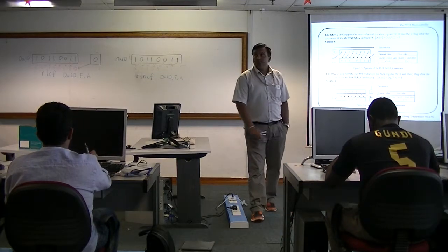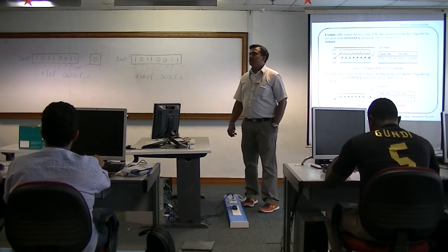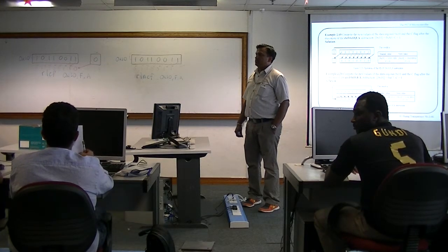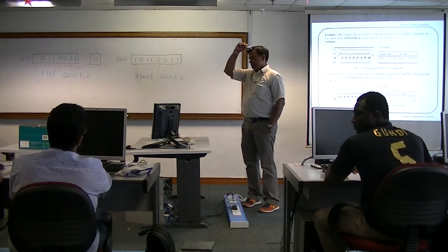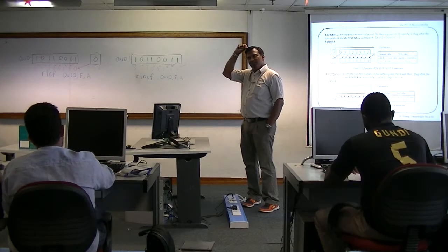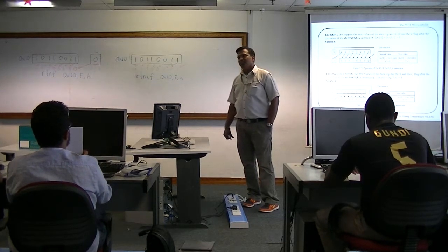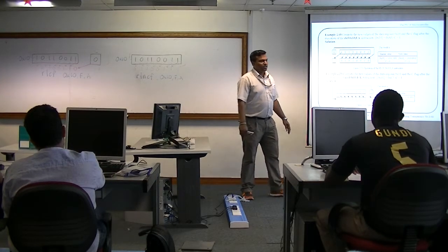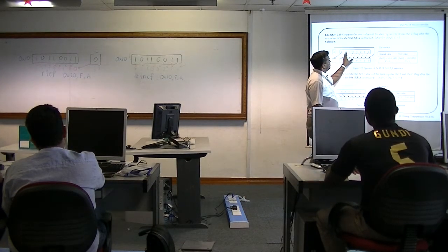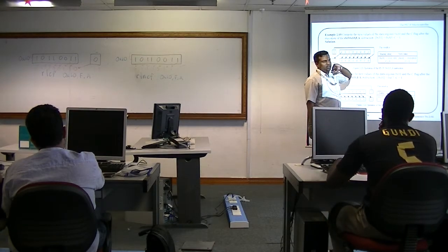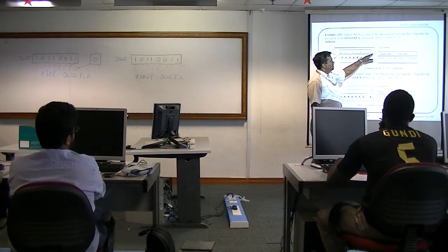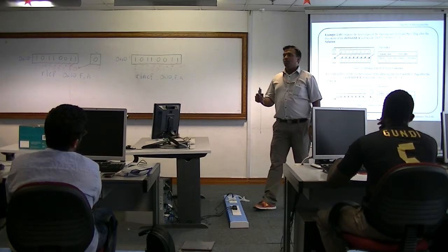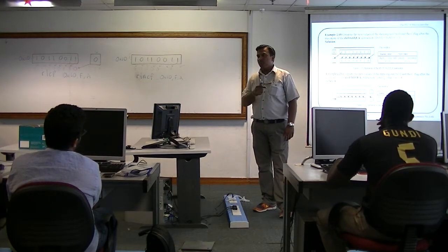So, yes, Stephen. This diagram with the carry is right and left. Example 2.19, carry is left. Doesn't matter, the principle is the same. When you rotate left, remember whenever it's through carry, whatever is inside the carry should be pushed first.